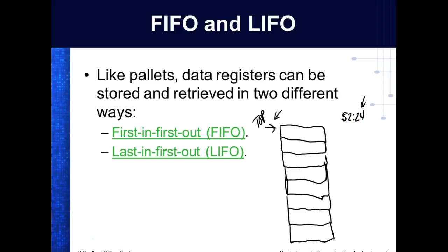A lot of your instructions, like your counters, use the status register to keep up with the status bits, your done bits, and the other ones for counters: counter done, enabled, overflows. All those are up in your status register.